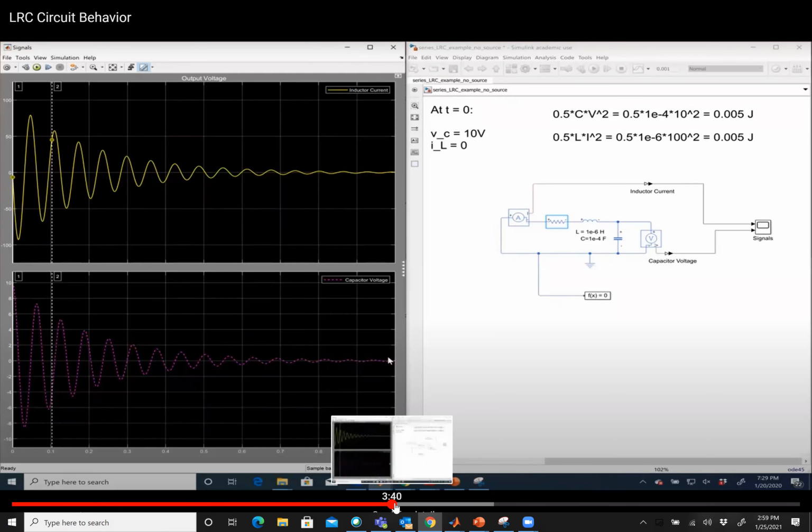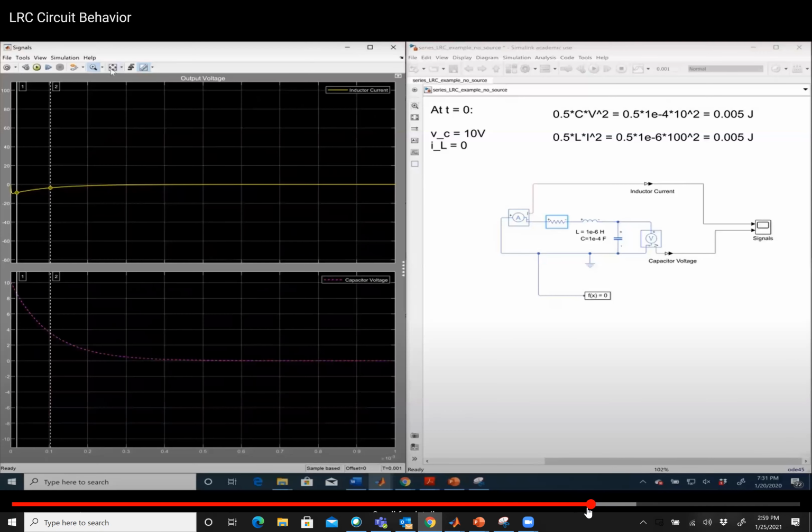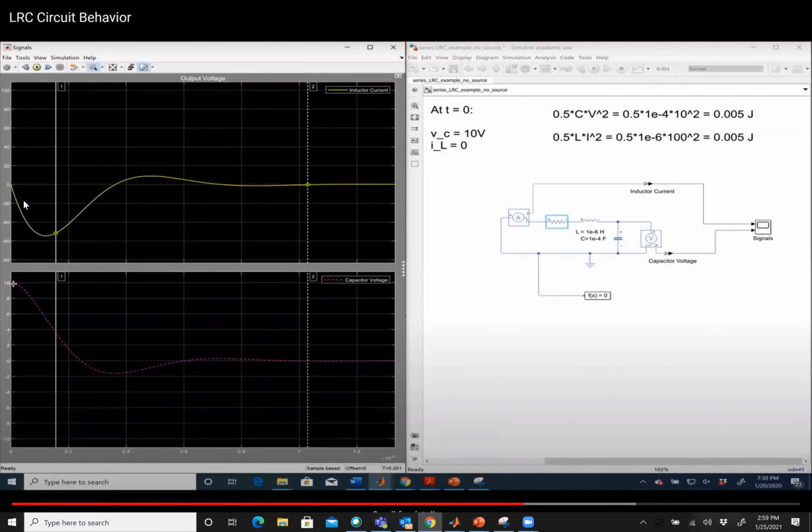And if I continue to increase the resistance in the circuit even further, right? All right, this is with a slightly higher resistance. I still see a little bit of oscillation. What I call this is a little bit of overshooting, where if I look at the voltage, it goes below 0, then it goes above 0. So it's that below and above 0. Sometimes we call that overshooting, okay? This is also what I would call an underdamped response.